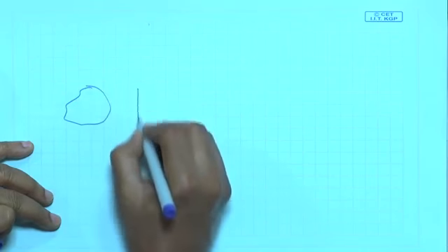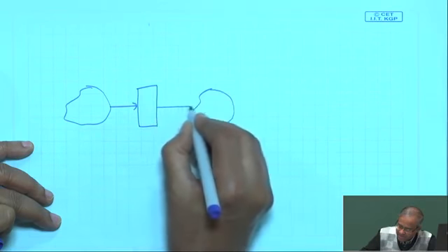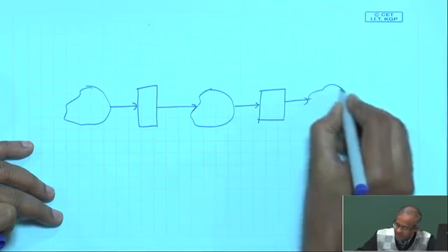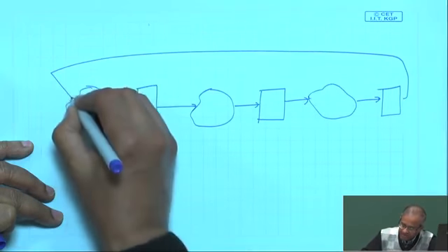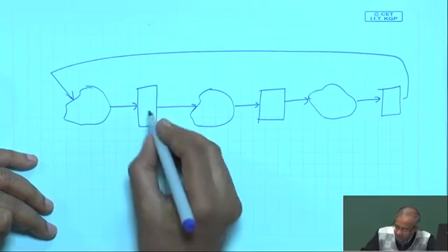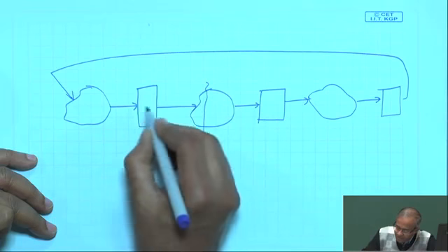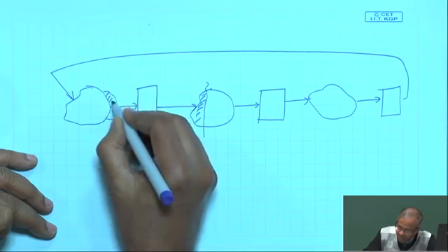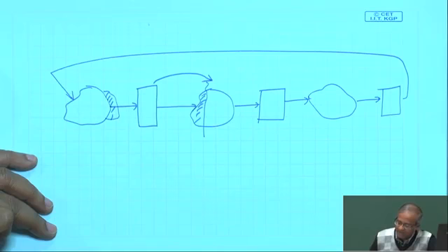You can have a scenario like this. You have some combinational circuit, then a flip flop feeding like this, then a combinational circuit, then a flip flop. Maybe you have something like this, maybe something you are feeding back like here. Now, this combinational circuit can consist of a number of gates. It is possible to bring some part of this circuit along here or the reverse, and move this flip flop a little ahead in the chain.